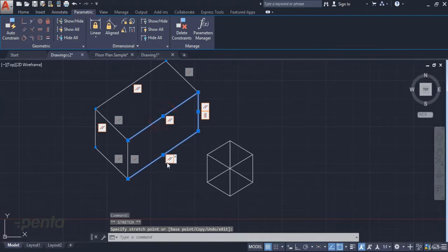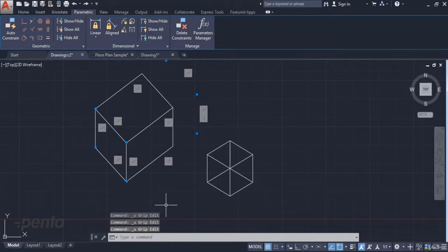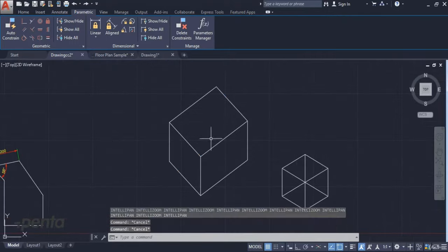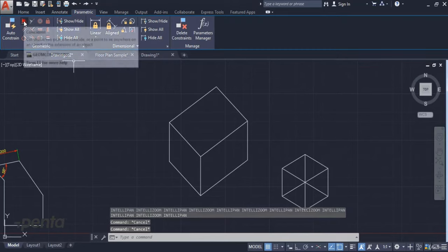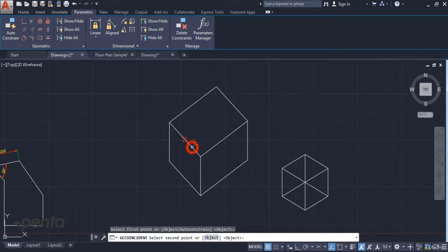We can make changes and manipulate parts without deforming or distorting them. Here, if you'd like, we can try this manually. Here, we can use the coincident to add two lines end to end. Sorry, I made a mistake. I'll try again. I wanted to grab the endpoint. Click here, and you can see here that it grabbed the point. I grabbed the midpoint before.